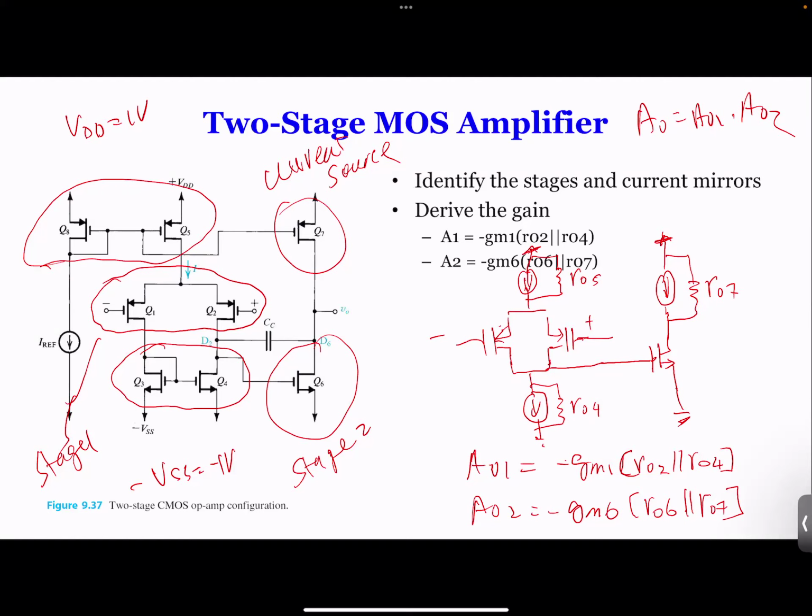It does not supply the current, and then the biasing is lost. If the DC biasing is lost, you no longer have an amplifier. That's where your circuit would experience the maximum input voltage. So at what point would Q5 lose the capability to provide current?